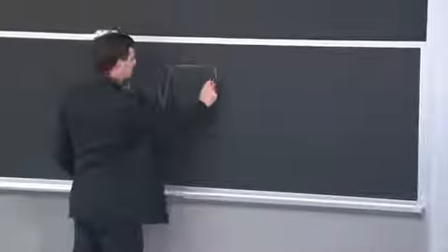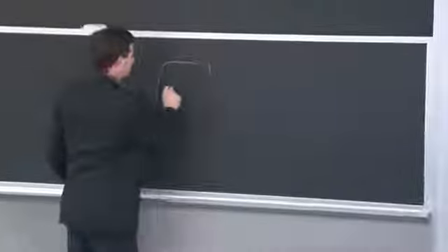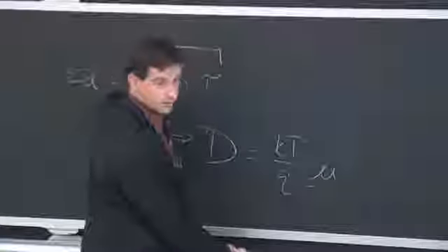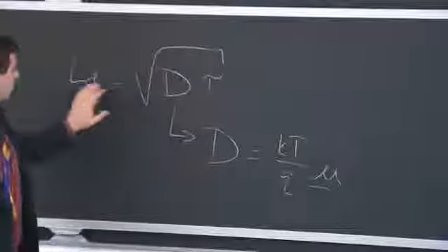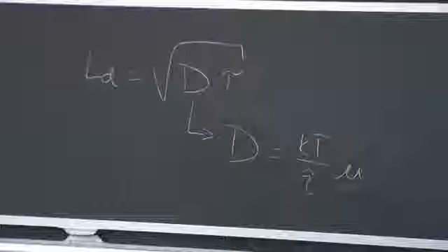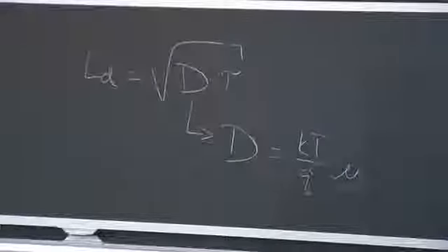One very simple way to think about it is, at least for a band conductor, you would have a certain diffusion length, at least to first order, would be the diffusivity times the lifetime. And the diffusivity would be related to the mobility inside of your material. So your mobility is factoring into your diffusion length, and the diffusion length is affecting how many charge carriers are collected. So that's a simple way to think about the problem.